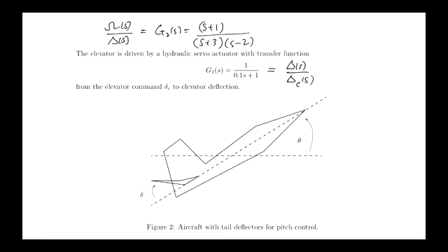So we're given models for how the pitch angle, the angle of this actuating surface, relates to the pitch rate, right? So that's why I've written omega here instead of theta. Omega is theta dot, right? So in the Laplace domain, it's this, all right? So what we're interested in doing is trying to regulate the pitch rate to a reference. Okay.